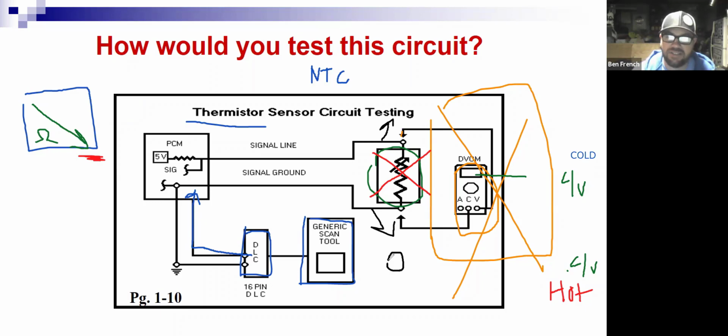In fact, it should be out of limits, infinite resistance, because it's not hooked up to a sensor. Remember we said cold is high resistance. So I've created really high resistance by disconnecting the sensor. My scanner right now with the sensor disconnected should read like negative 40 degrees below zero. Boom, freezing cold when I disconnect the sensor because it went really, really high resistance.